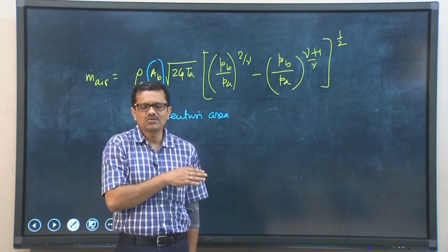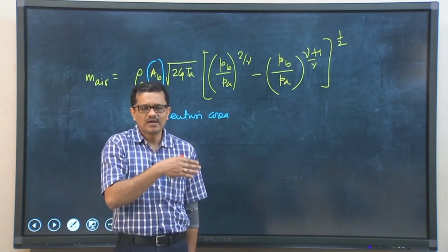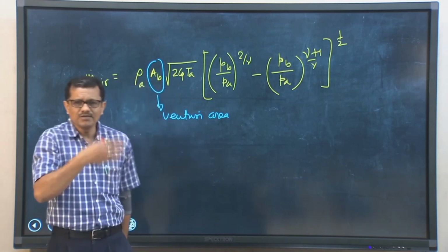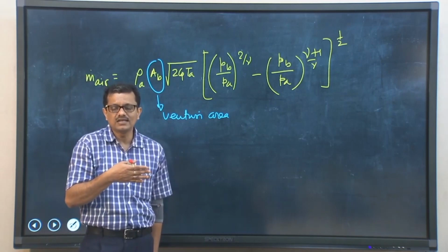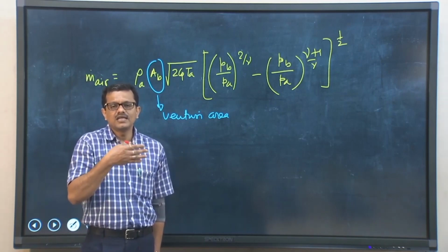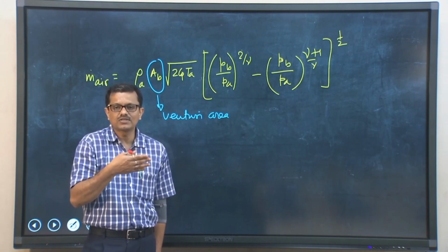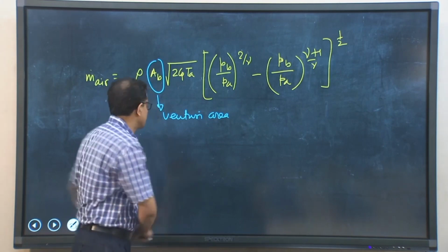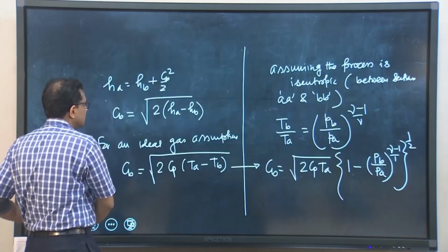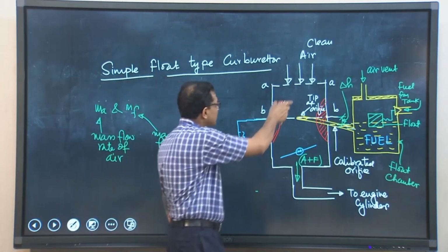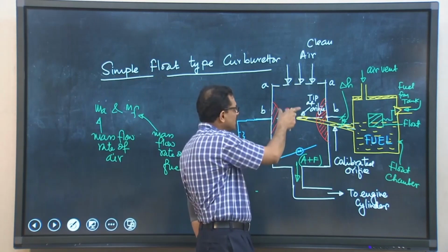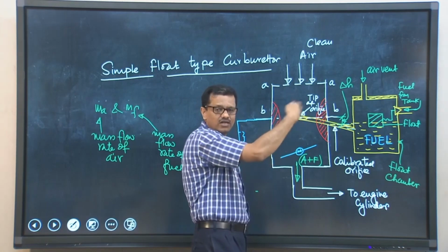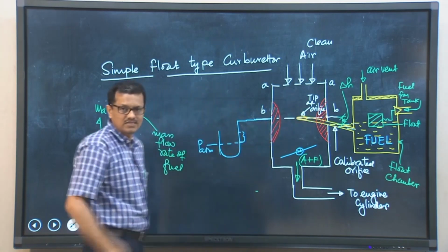But though there is no heat interaction, the process is not involved with any type of heat and work interaction, we cannot trivially ignore the frictional effect, because though the viscosity of air is very small, still it is bounded by the solid walls. So, if we go to the schematic depiction, when air is trying to flow over this, there is a constricted passage, moreover solid surfaces are there, so a boundary layer will form. So, basically we cannot trivially ignore the frictional effect.